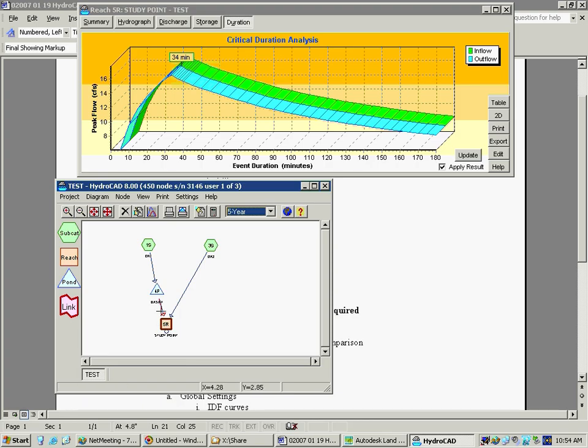And what you can do with this is by actually routing the model all at once. Let's say you had 3 basins. You could have a first flush, which let all that water out initially, and then you could have a slower acting basin, which let some water out midway through the storm, or just retained more water. And then you could have a basin that retained a lot of water, like maybe an infiltration basin, or just one with a 3-inch water quality orifice or something. So what you can do with this method is spread your hydrograph out over a much longer period of time, and it knocks that peak down.